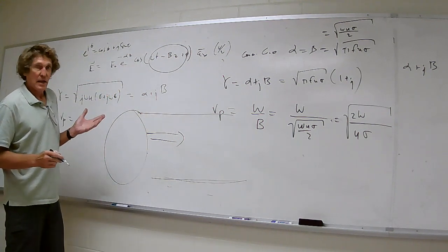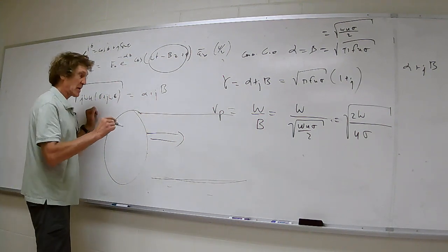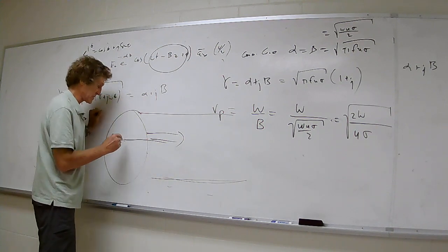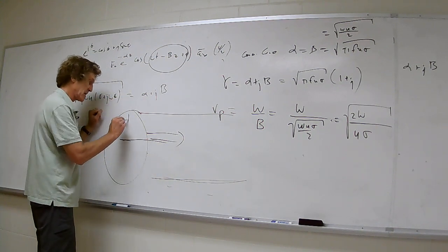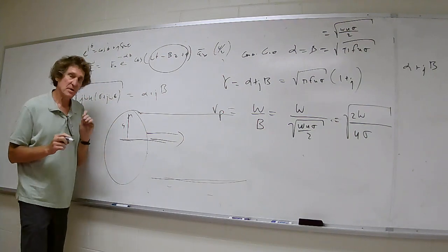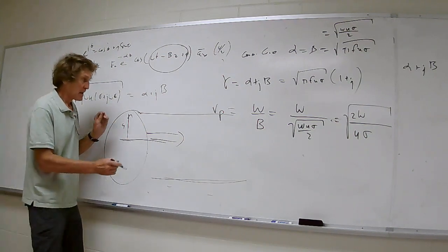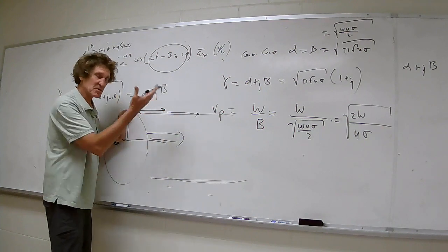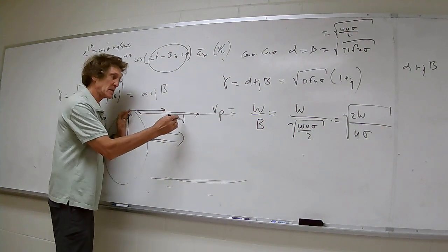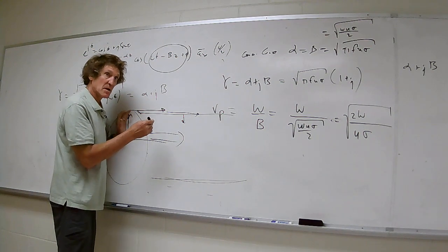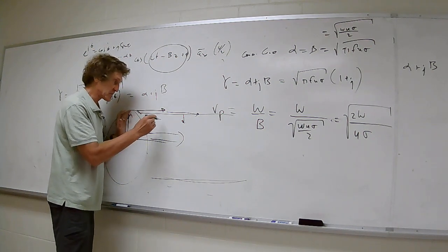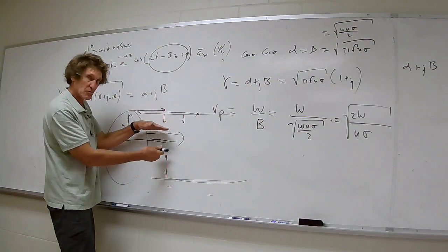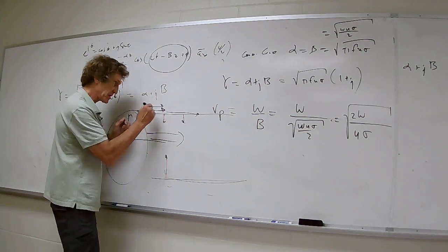And it can be in a coax cable, but anyway, I want to focus on this. What you're going to see is this. As current flows, if this has a given radius A, I just want you to appreciate the big fat wire. When the electric field is on the surface, it'll short out before it can get any depth into there, because there's a wave that's propagating from the surface of that copper wire towards the middle. The electric field is in this direction.